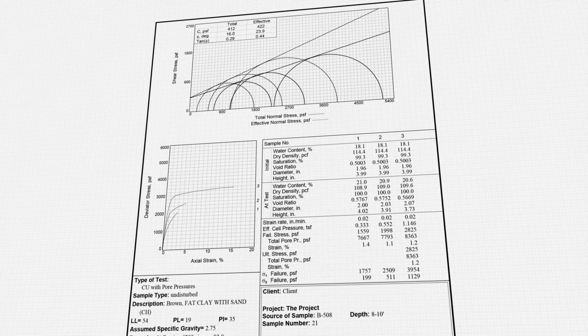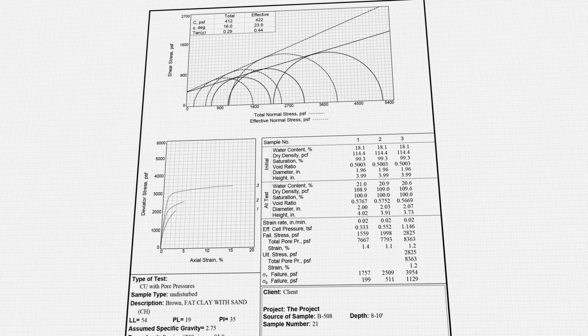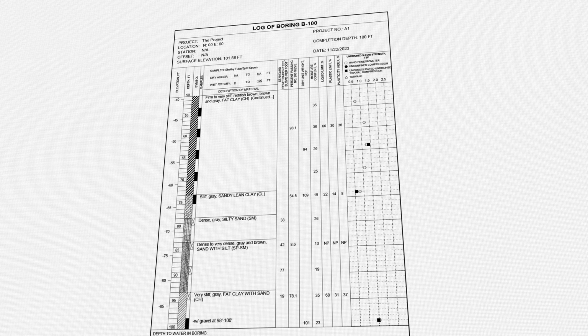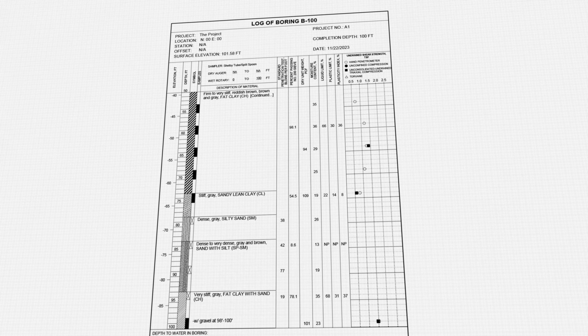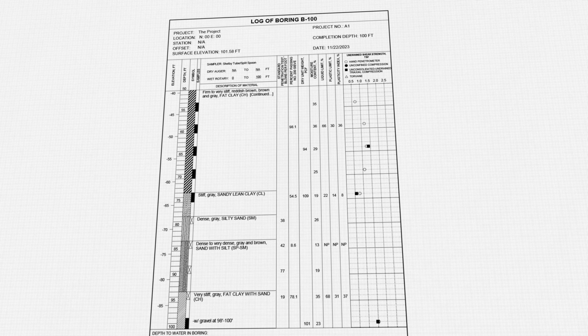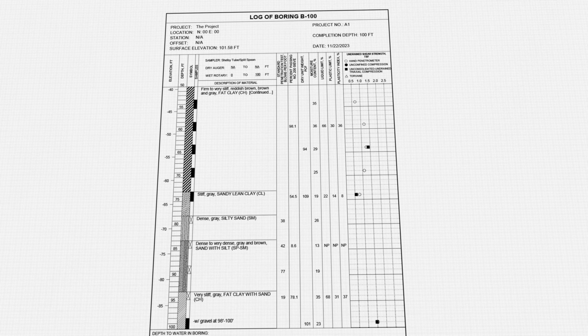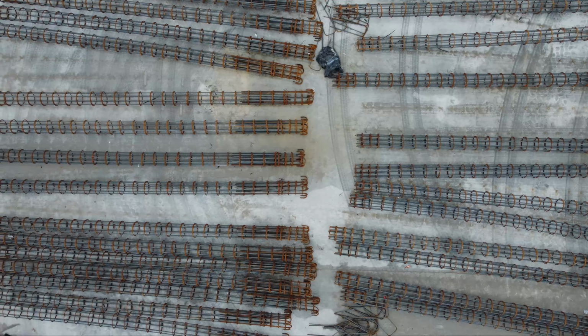The geotechnical team will produce a formal report describing soil conditions and listing different soil capacities. Boring logs are also included in the report, so engineers can see changes in soil layers. This report will later be used by many other engineers as one of the inputs for their calculations. With preliminary field investigation completed, it is time to focus on engineering.